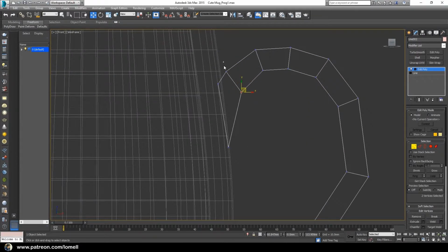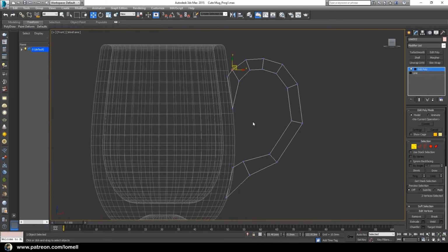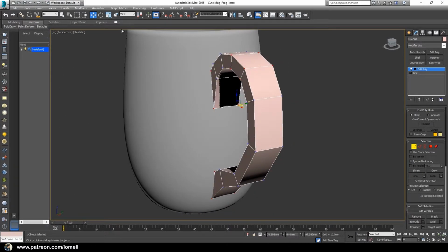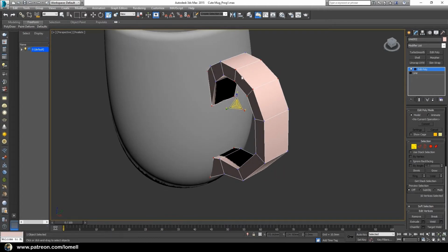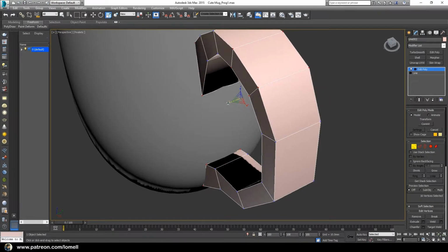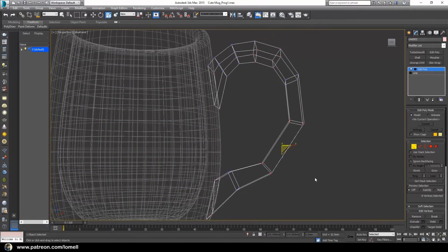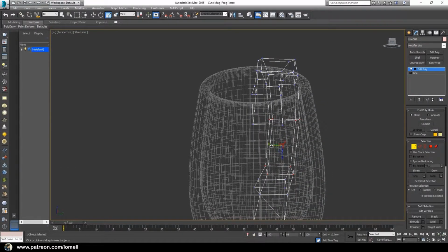Okay, so you may also want to pause this video at this part and copy this shape exactly as I'm doing in here. Okay, and if you're done, now let's select these vertices, including this. Okay, and now go back to perspective and press F3 and use the scale tool, and we're going to scale these selected vertices in y-axis just a bit. Okay, press F3, select these vertices and scale it down in y-axis as well,